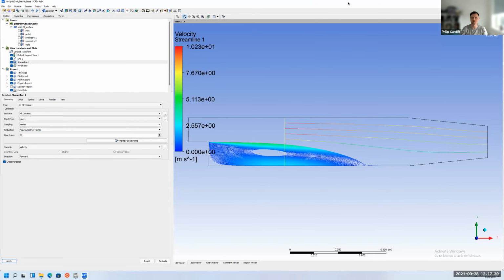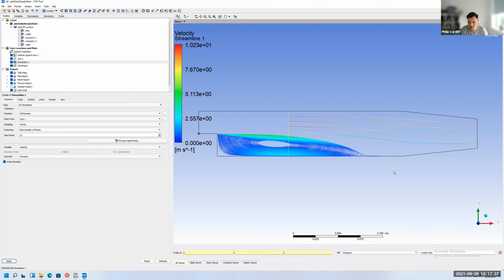So how can we measure that precisely? We can use a probe or a query. If you click over here, this little thing is a probe or a query. You can click a point maybe around here or here. It's a little bit ambiguous. You can see it gives coordinates of 0.19. Maybe you could say it's more like there, so 0.186. The experimental answer for this, I think, was 0.179 or something, plus or minus a certain distance. So we're pretty close to that at the moment.